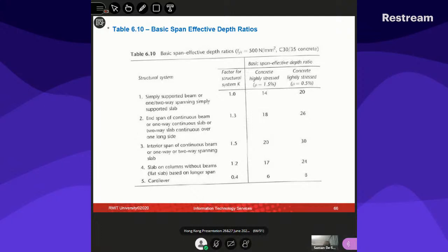If you give a floor depth, mind you that if you have beams, there should be services and other things running as well. So you have to at least allow 300 millimeters between the ceiling and the bottom of the beam to have the services run,